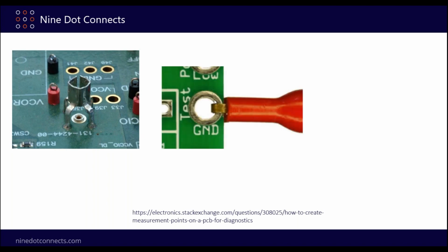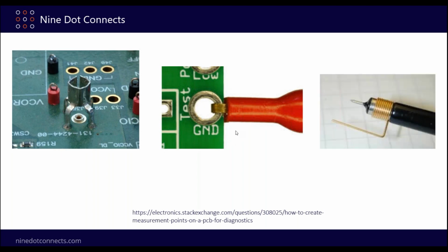There is also another mechanism over here. This is just kind of being smart about it so you don't have things draped all over your board. And so keeping that stuff off to the side is really, really helpful. And then lastly, over here as well, you've got 2 pins. So you've got the pin over here, but you also have your ground. You have to remember that these pins, in a sense, are binary tests. So even though it's testing for some type of function on a single signal, you have to have a reference to something. And 99% of the time, that reference is going to be to a ground.